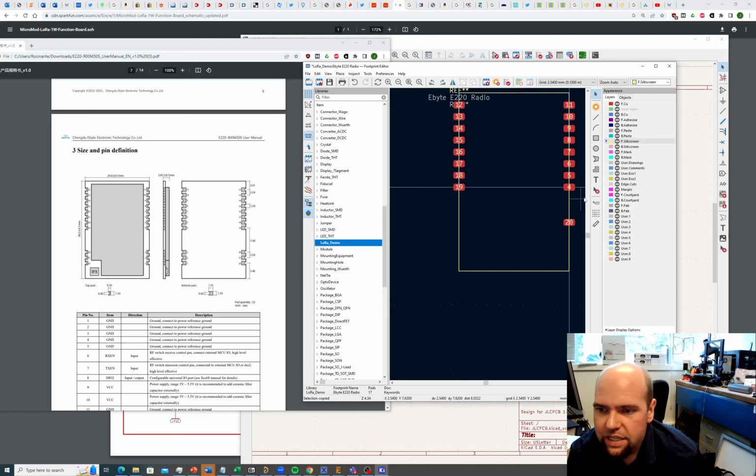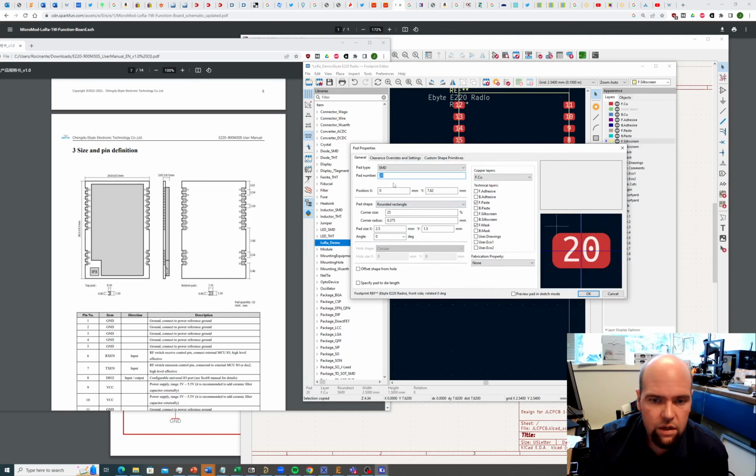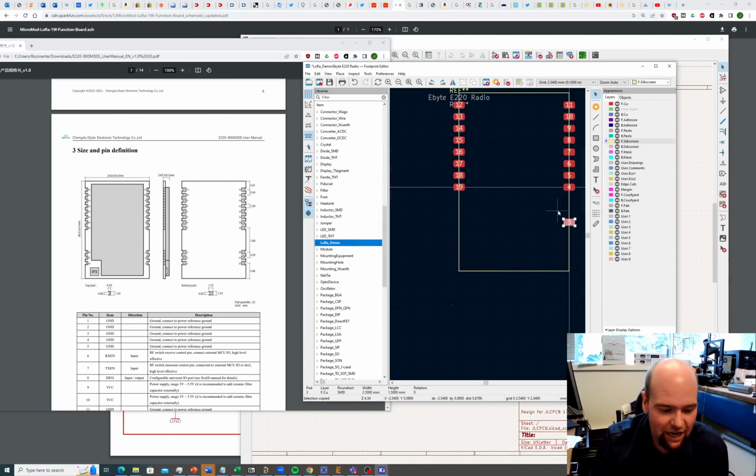It's got to be 7.6 inches from this bottom pin here, which is already our reference, so we're good to go. So let's take this, and we might as well just call it pad number 3 because we're here. But the Y now, oh, that's interesting. Not the size. Sorry, the Y here, 7.62 is what it wants, which my guess is what's actually correct. But it should actually be 7.60 according to the data sheet, which I assume is wrong.